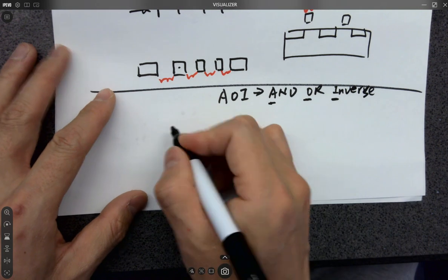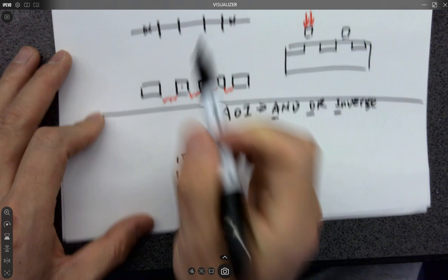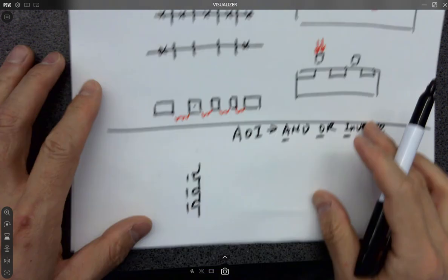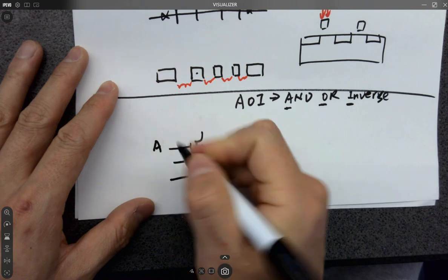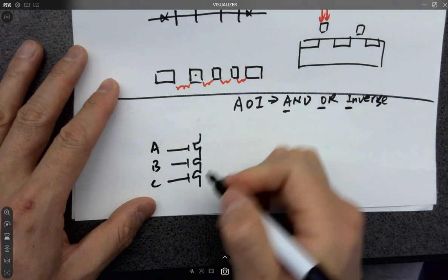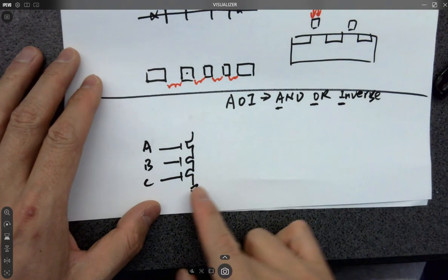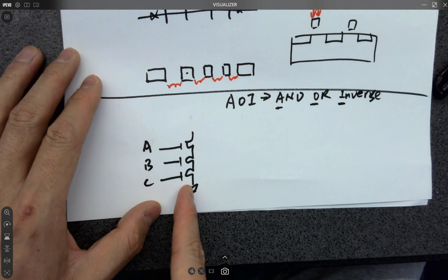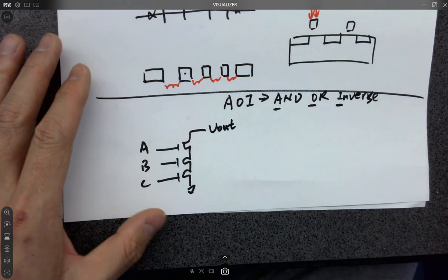So for example, if I draw this, 3 transistors in series, similar to this schematic, okay? 3 transistors in series, and I got 3 signals connected to the gates separately. And definitely NMOS is good at passing zeros. That's why I short the NMOS, the last one source, to ground, okay? If this is the VL, so VL equals what?